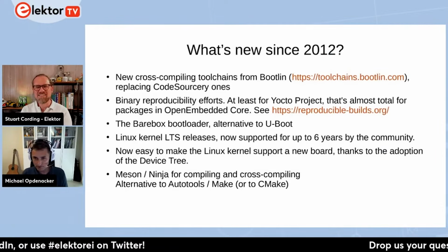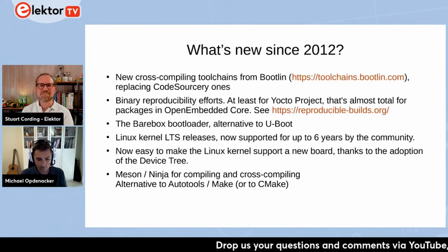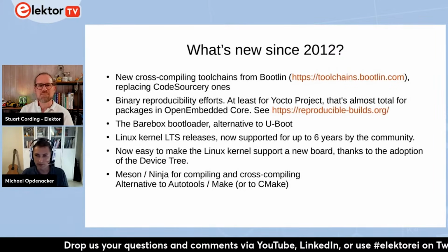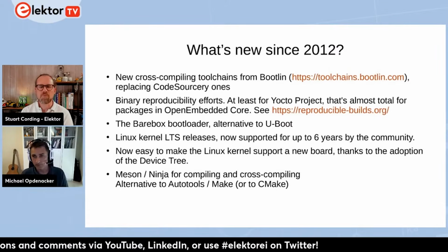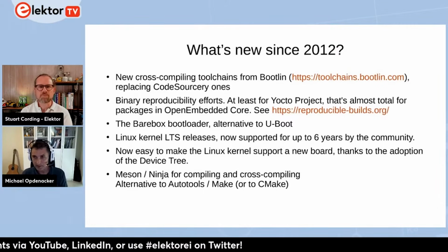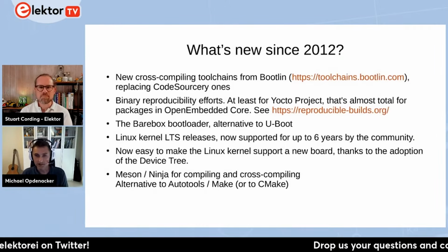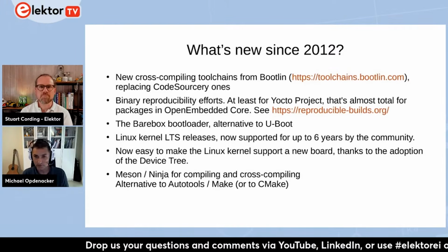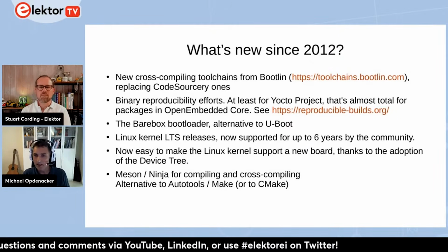Maybe people remember the CodeSourcery toolchains to cross-compile your software. CodeSourcery is gone. They've been sold to Mentor Graphics, and they don't release interesting open source toolchains anymore. So we have worked on the replacement. If you go to toolchains.bootlin.com, you can find GCC toolchains for many architectures, many versions of GCC, and we really intend to make that available forever if possible. So that's a good, useful resource, I think.